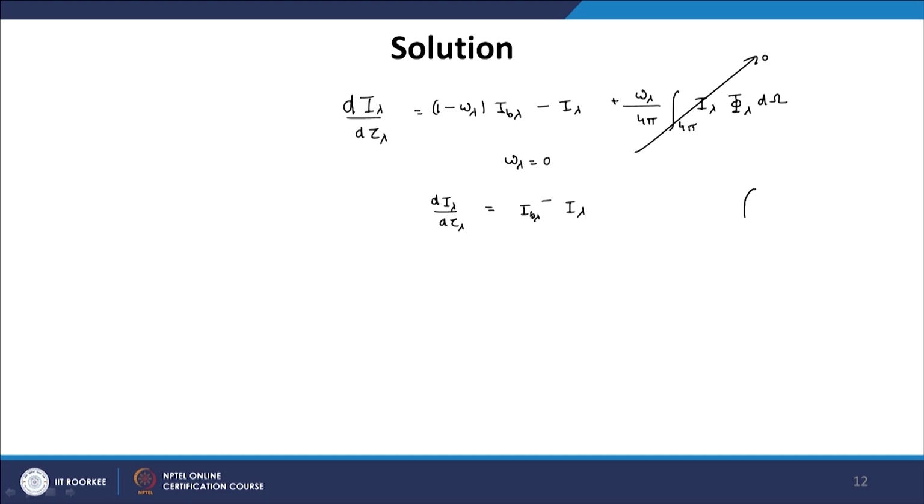Now, let us look at it. This is in a given direction. So, we draw our sphere again. So, we are looking at the intensity at this point. So, this is our intensity I lambda in a given direction, let us call this S cap. Now, where is this intensity coming from? This intensity is coming from this part of the sphere, this is the center of the sphere. So, radiation along this path we have to calculate, this is the path. So, it may start at this point and it may go all the way up to this point on the sphere surface.